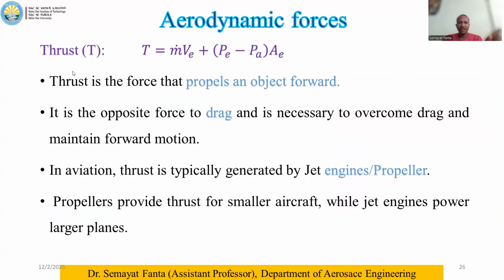So the thrust force in the aircraft is related to the mass flow rate and the exit velocity. Exit velocity VE means the velocity of the exhaust gas. The hot, high-pressure, high-temperature gas from the combustion chamber comes through the narrow section of the throat and accelerates through the exhaust, so that the exhaust gas velocity is this one.